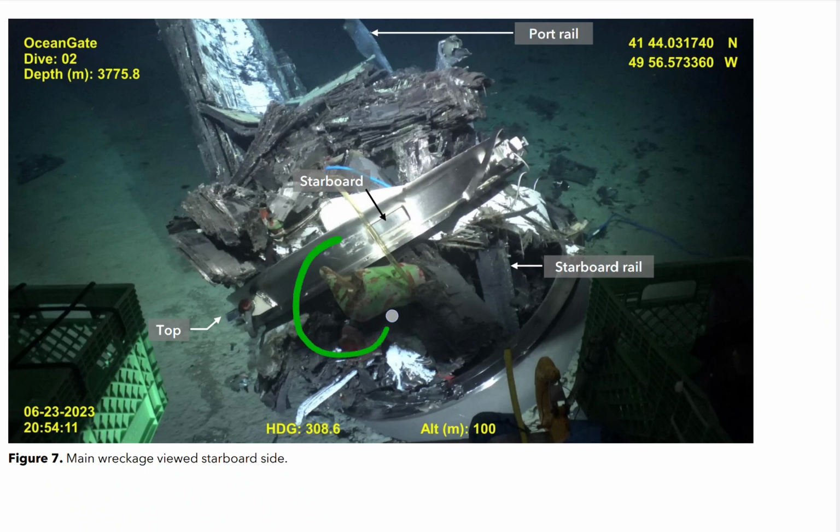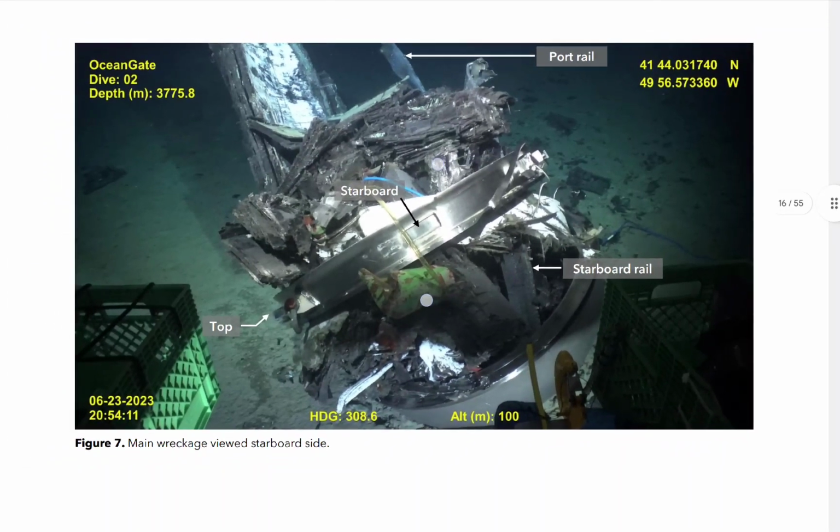I mean, look on the outside of it. There's a buckle there now. Could it be an implosive buckling? No, I've seen the implosive buckling of bottles, and they look like this. This might be aluminum. It might behave differently. I don't know the rib structure of that. I would like to know the design of it. But it's like it's folded over the impact, so we're losing a lot of material here. I do not think the carbon fiber had the ability to crush that tank.